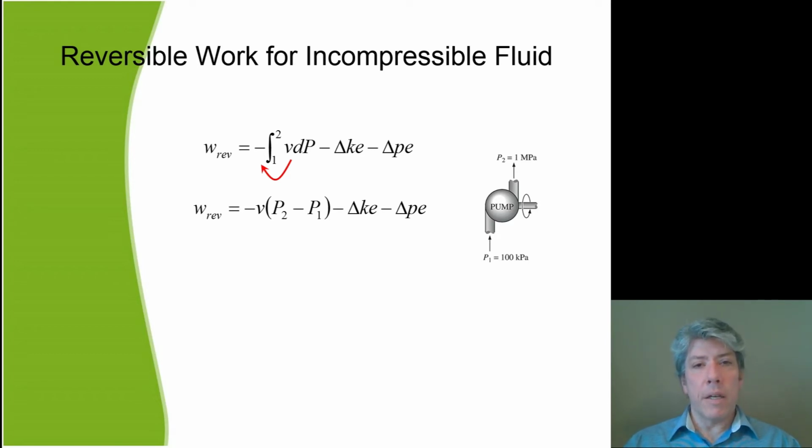And you might not recognize it right now, but that first term, V delta P, is an equation you would have used. That would be the primary portion of the fluid power change across the pump. Often the kinetic and potential energy changes are negligible. Now this is not always the case. Some pumps are really good at generating kinetic energy, but not necessarily changes in flow energy, which is the V delta P term, the pressure change term.